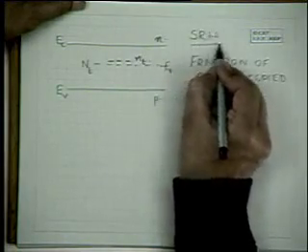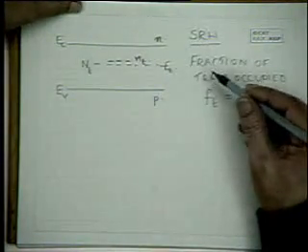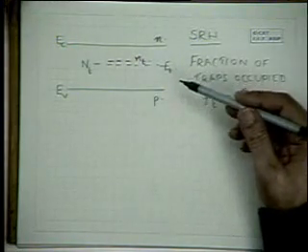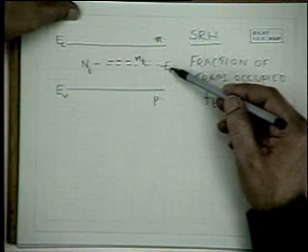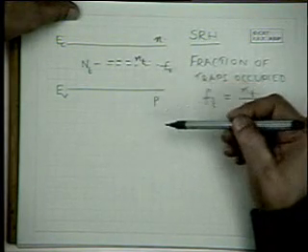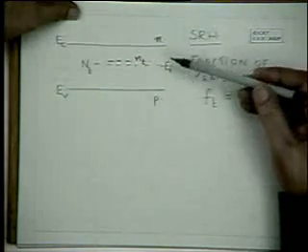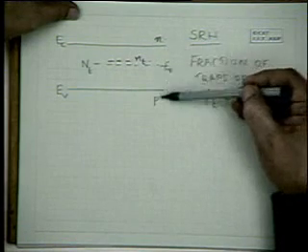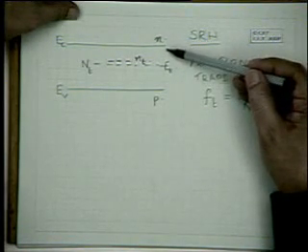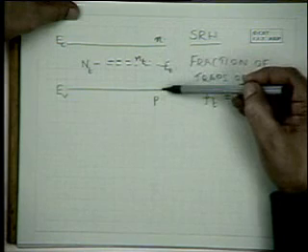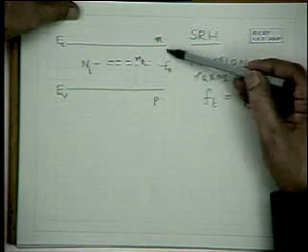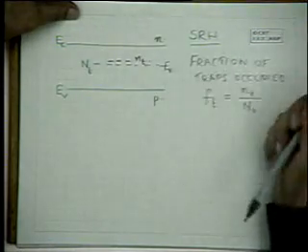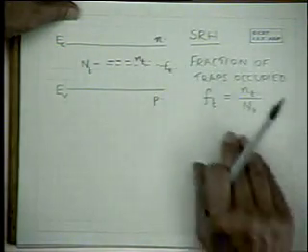We are looking at the SRH model, and from this treatment we hope to calculate what is the lifetime of carriers in this material with a single recombination center somewhere near the middle of the band gap, and what happens if the Fermi level in the material varies through the band gap. When it's highly n-type, the Fermi level is here. When it's highly p-type, the Fermi level is here. And as the Fermi level is moved through the band gap, how the lifetime varies. Okay.